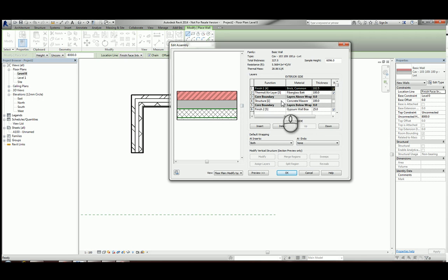So basically what we do when we're creating walls is we put the structural element between those core boundaries. I know in a masonry wall the whole of the construction can be load bearing and can be the structural element, but more cases than not we just tend to have that part of the wall just there as a structural load bearing element within our wall. For example, if it's timber frame, light gauge steel, maybe even a masonry thin joint or a concrete framed building, that would all be the structural side of it, and any brickwork outside of it or block work with render is basically just a rain cladding, that's all it is.